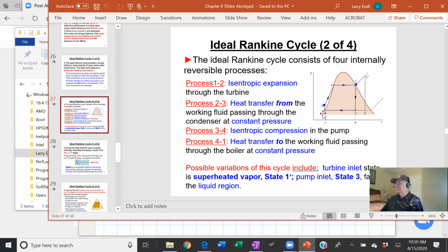Let's forget about this and look at the real cycle. The real cycle, say coming out of the boiler, again, you're bounded by upper pressure. This is a constant pressure line here, comes here, and then goes down like this. And then this is a constant pressure line here. This can be typically 80, 100 bar. This is like 1 bar or less down here. So you go into the boiler, and once you get into the boiler, you hit the boiler pressure. This is a constant pressure line up here, 80 bar. This is in the compressed liquid zone.